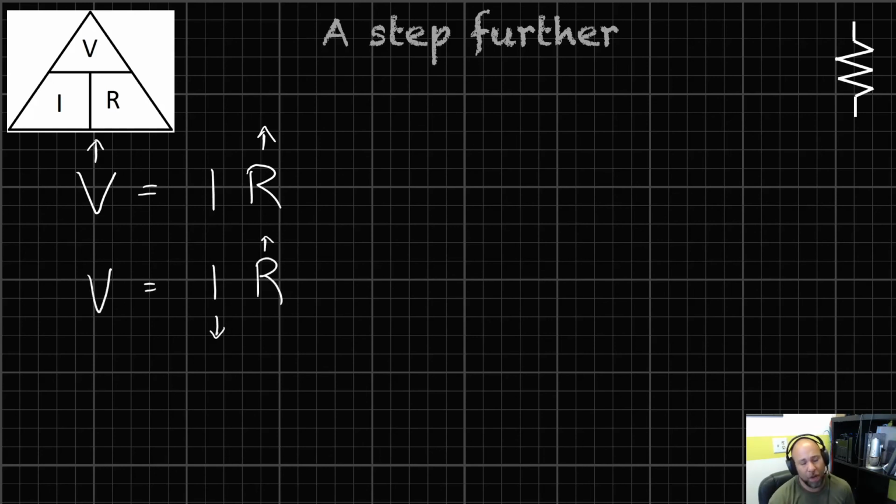At the same time, if our voltage, our pressure going through the system, is remaining fairly constant, and we can see that our current, or the flow of our system, is going down, well, that must mean that somehow, some way, our resistance is increasing. And then one final practical example, if we notice that our voltage, our pressure in our system, is decreasing, but our current, or the flow within the system, is staying the same, that must also mean that any resistance, any barriers, have also been proportionally decreasing as well.